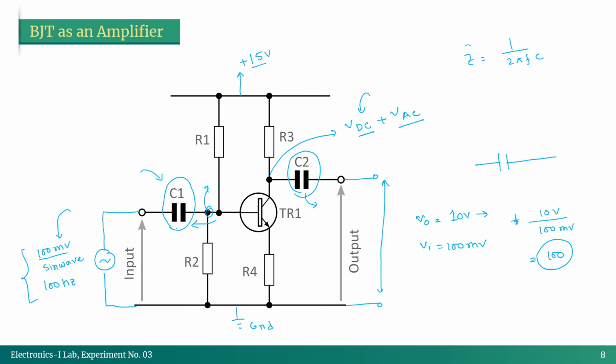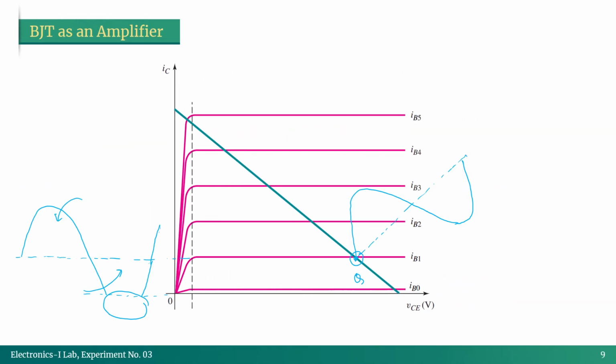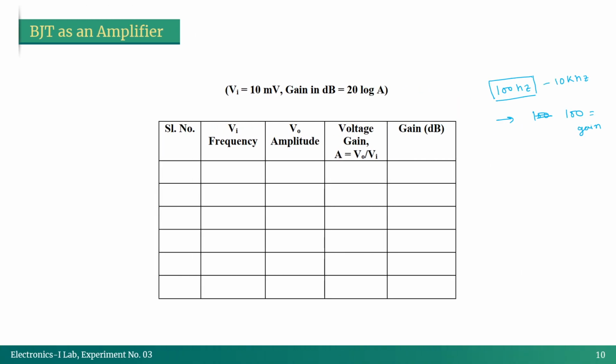This can be thought of as the resistance-like behavior of our capacitor. Whenever we change the frequency here, obviously this impedance will be different. So the voltage drop here will be very different for each particular frequency of input. That's why we are going to get different behavior at the output.